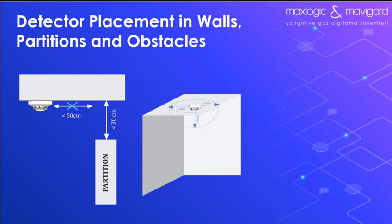Where rooms are divided into sections by walls, partitions, or shelves that extend up to within 30 cm of the ceiling, the sections should be considered as reaching the ceiling, and each section should be considered a separate room. A gap of at least 50 cm should be left in all directions around each detector.